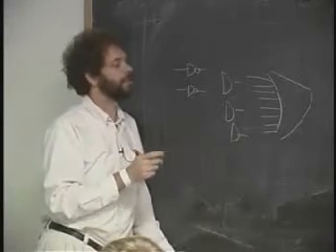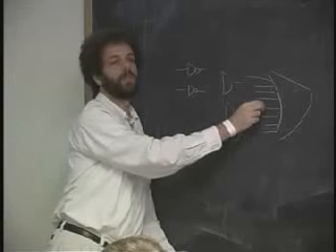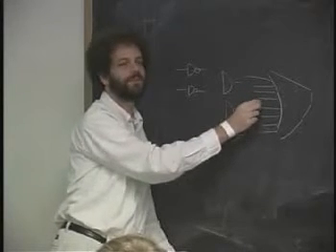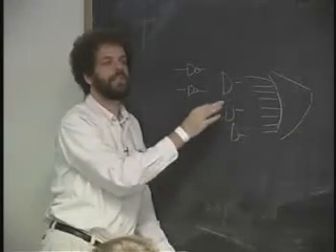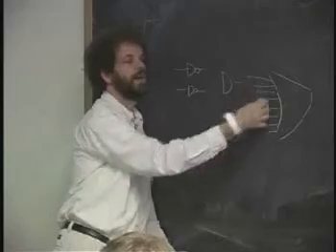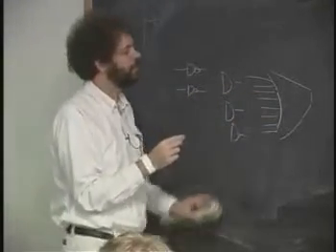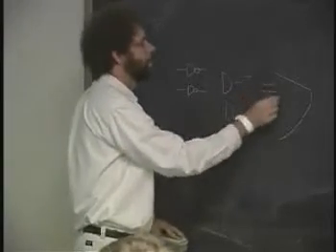And the reason it's not true is that if you put 2 to the 30 wires on here, it's no longer 1/billionth of a second. It's now, you know, 100 seconds, or something awful. So infinite fan-in is not a valid abstraction. Fan-in is a measure of how many wires come into a gate. What's more reasonable is to say that there's finite fan-in. So this can get to, at most, let's say 10 wires.